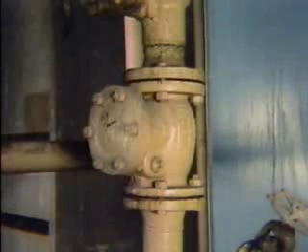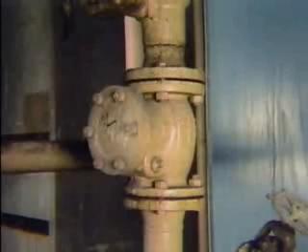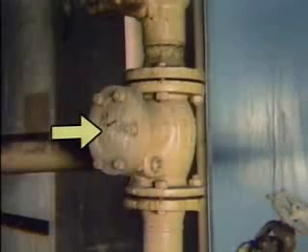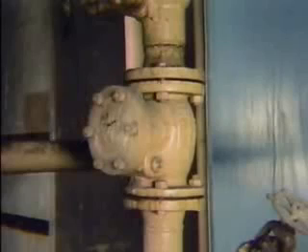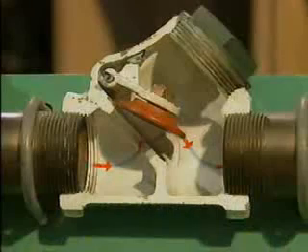The body of a check valve is similar to the body of a globe valve, but most check valves don't have stems, handles, or hand wheels. Most check valves do have replaceable seats, discs, and caps. The cap is the top part of the valve body, which can be removed to provide access to the disc for maintenance. It's essentially the same as the bonnet on other types of valves.